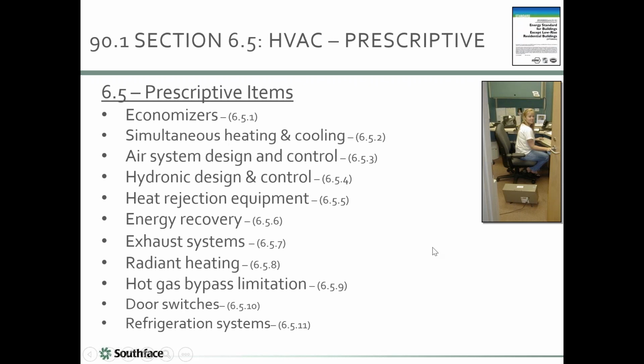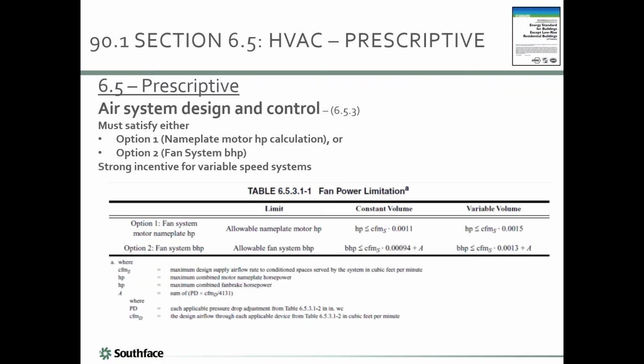All right, that is the ASHRAE 90.1 approach to mechanical systems. Oh, and I did want to show this. I think this was good. This was the only calculation you have, and it's basically saying you can't run too much air through too small a duct. So designers need to be aware of this in the sense of we've got to leave room, architects need to leave room for big enough ductwork. And it definitely incentivizes variable speed blowers, which we absolutely want.